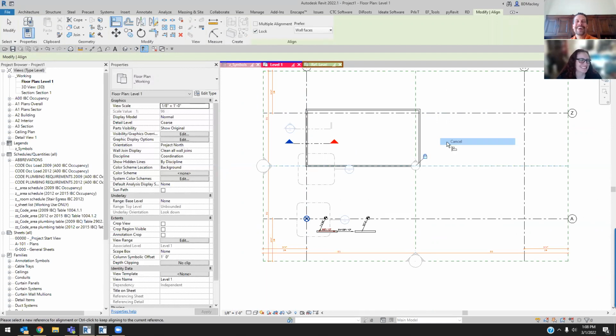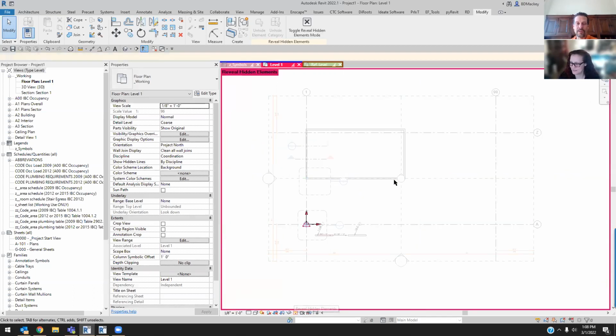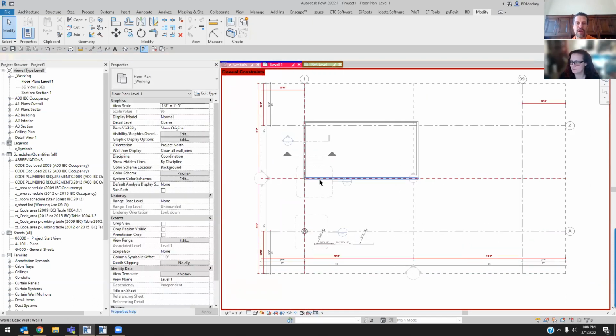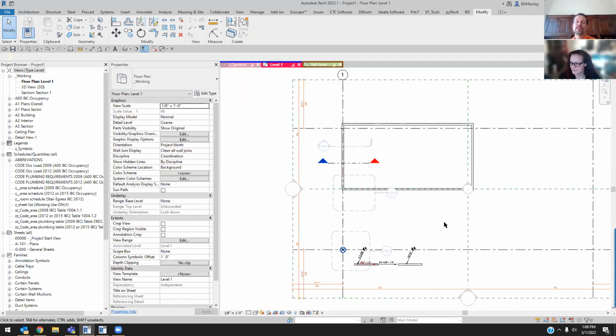Yeah, I was doing something, I'm like, what did I do? I just closed out of the file because I realized it was happening. I'd been in there like 20 minutes. I'm like, yep, I'm gonna go redo what I did because I don't know what I did, and that takes so long. In hindsight, after I closed out the project, I did realize that, oh man, you're an idiot. You probably could have used Reveal Constraints and found all the things in red. Damn it. But it was hindsight. But yes, be careful with the align command in Revit 2022 if you guys are in that.